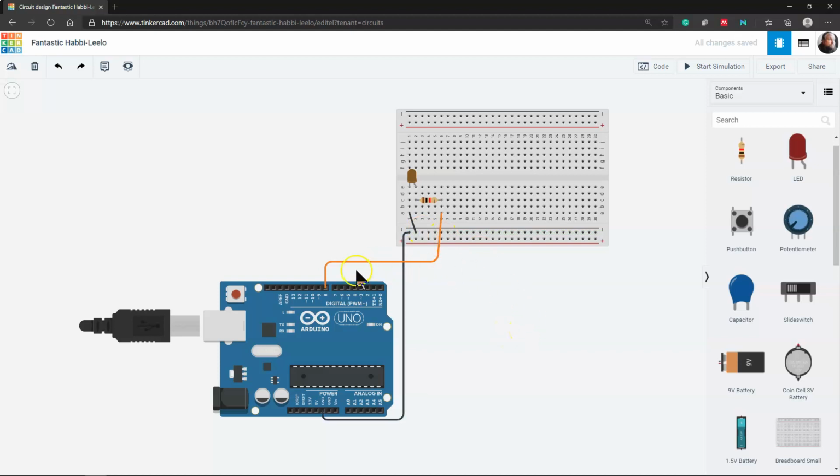So what we have here now as a circuit is that pin 8 will be our power source, where in code we can control it to be on and off. And so from here, it'll flow through here for the power when we turn it on, up through the resistor, everything else here, and then back down to the ground, and that becomes your power source. But the difference here is this always provides power. This is then in your code. You can then control to do what you want. So we've got everything wired up, so now we need to go and start coding everything. We need to remember that we've decided to use pin 8 in this case.